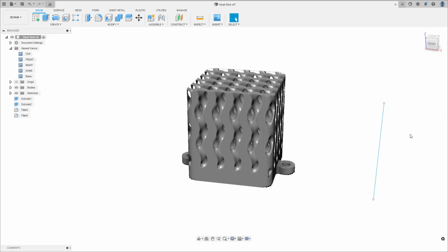Now we've designed our heatsink, we need to manufacture it. To do this, we need to convert our body, which has volumetric information, into a mesh. Certain 3D printer manufacturers require mesh as an input, whereas others accept toolpath data from print preparation software. In this first release, we focused on the mesh conversion workflow, as it ensures compatibility with the largest number of machines, processes, and existing workflows.